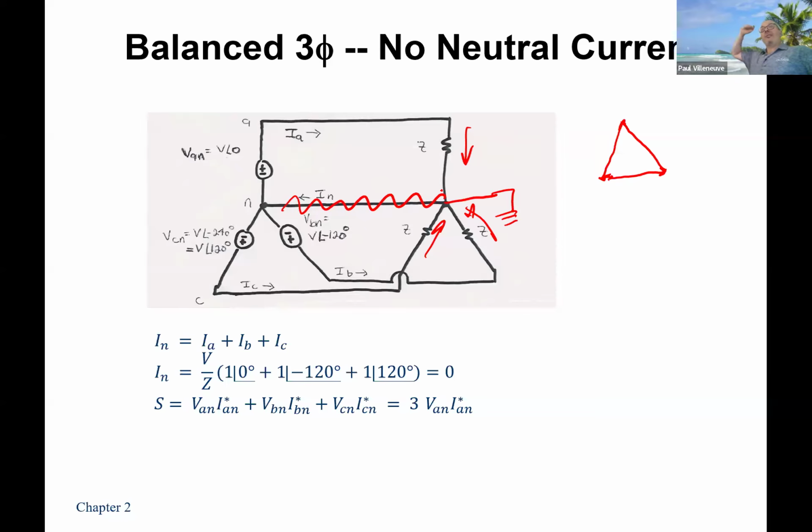So the utility system that you see, a three-phase system, like when you see overhead transmission lines, those are 3 hot phases, A, B, and C. And then usually overhead, not always, but usually overhead, you'll see a small bare conductor. That's your ground wire. That actually is not the ground that you think of. That's not the ground that interconnects the two systems. It's a ground that actually provides some lightning protection.